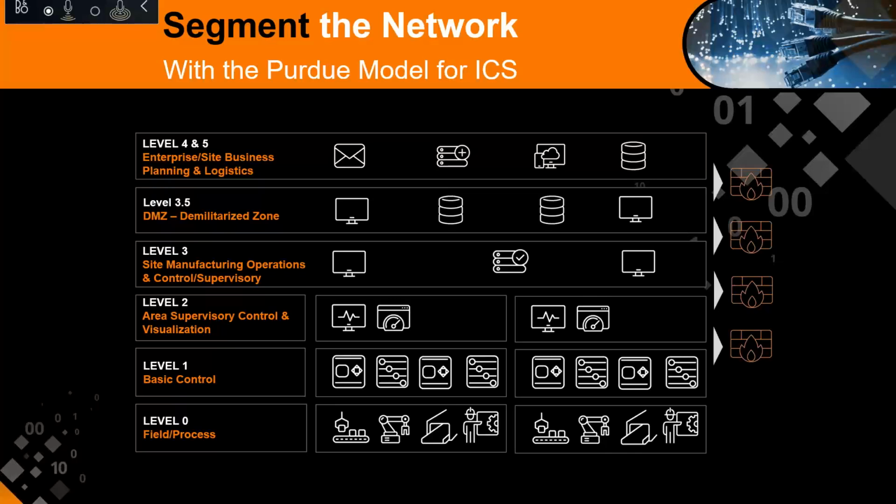But an IT switch is in general managed by the IT department. And in the IT domain, there are generally much more changes than in the OT domain. And changes basically means risk. So therefore, the better way to shape this is to physically separate the IT domain and the OT domain. Just put it on separate hardware if you get the chance.